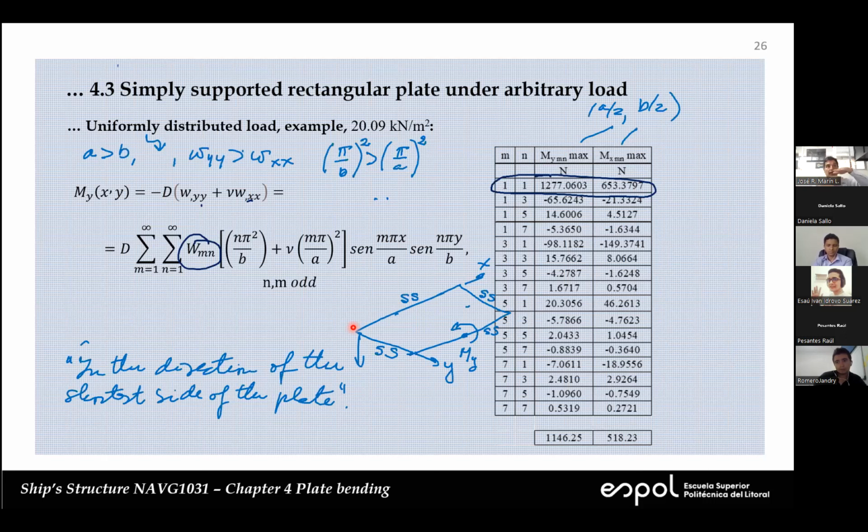Here, or in the middle of the thickness? Okay, so please be careful with that all the time. Because you will see in finite elements that you have many results. And one of the first things that you have to do is ask yourself, does this make sense? And the sign of the stresses helps you to answer that question.